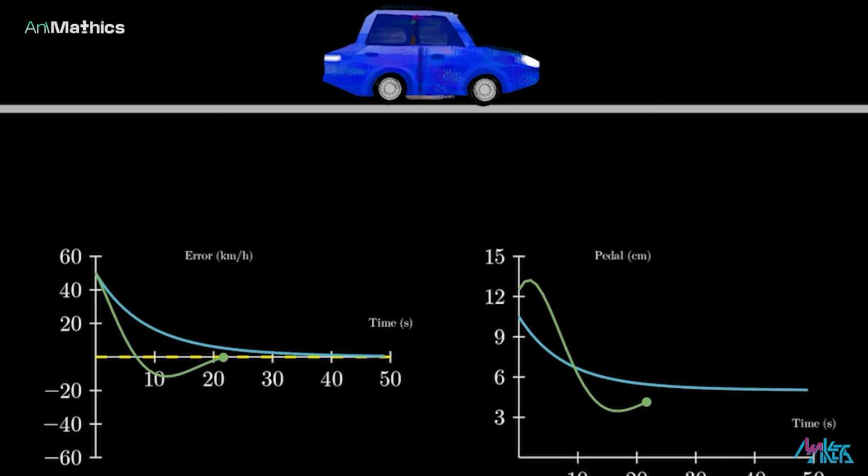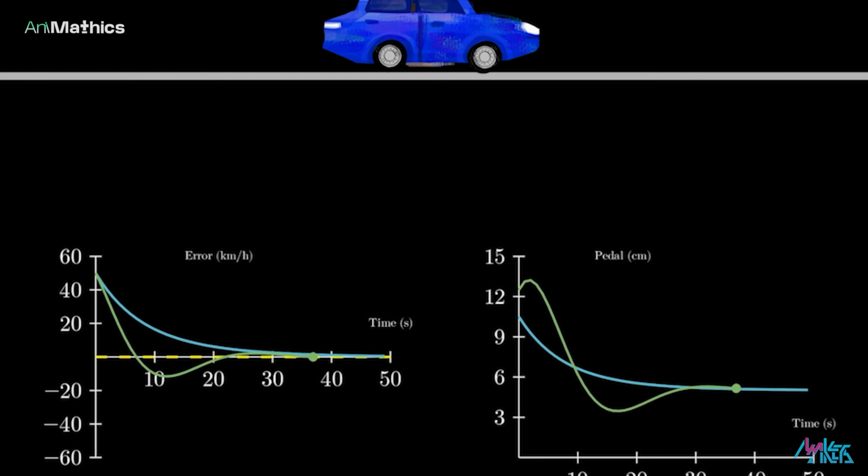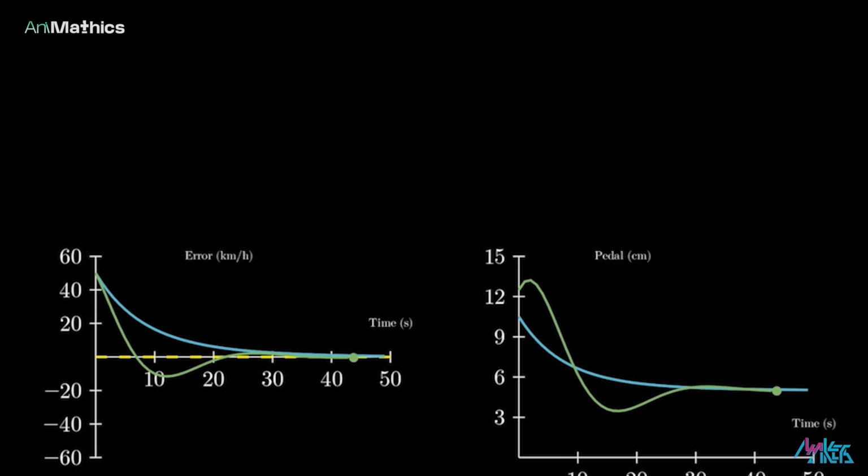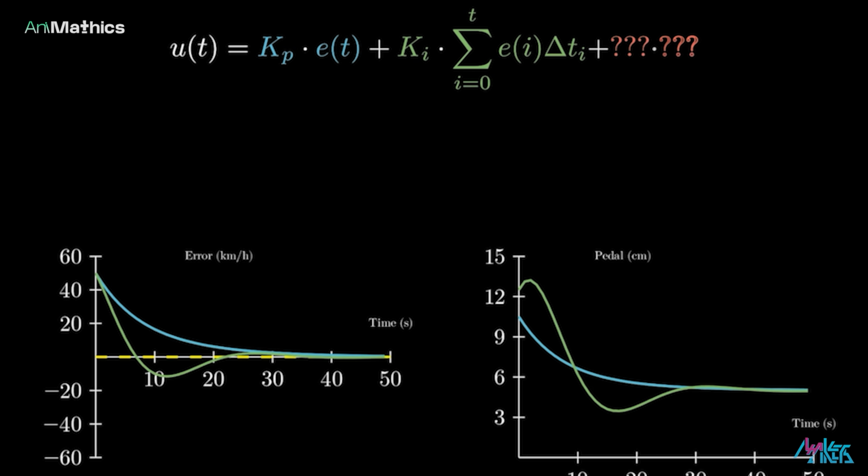At that moment, the speed overshoots and the system cannot respond in time. Even though the I part will then take negative values to cancel out the overshoot, in some machines, you don't want that overshoot to happen at all. This is when you need a part that can look ahead, a mechanism that can predict what's about to happen, not just react to the present and the past.